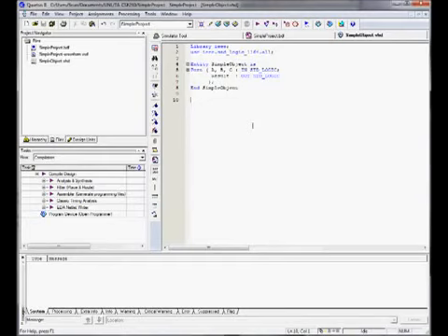Alright, so now we have a simple object, but we probably want to make it do something here. So let's define what it does. In order to do that, we need to create what's called an architecture for it. We do that by using the architecture keyword. So the architecture, and you can call it whatever you want here. So we could call it foo, I like to call it behavior, because that's what we're modeling here. We're modeling the behavior of our simple object. So the behavior of our simple object is, and now we must begin. Caps actually doesn't matter in this. Be sure that your variables are all named differently. It is not case sensitive, it will not pay attention to that.